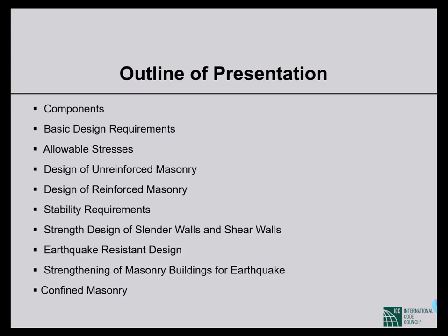But if the unreinforced masonry walls are also used as load-bearing components for gravity load, then this becomes very, very difficult, because in most cases it is found that due to lateral load, since the moment frame system is quite flexible, they experience a lot of drift or lateral sway, and that causes quite a significant amount of second order effect on the unreinforced masonry, and that is not addressed in the unreinforced masonry design methodology.